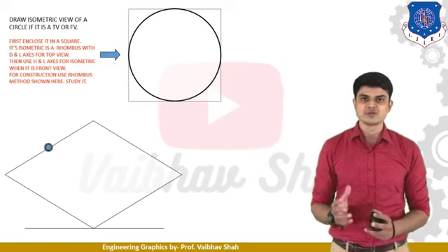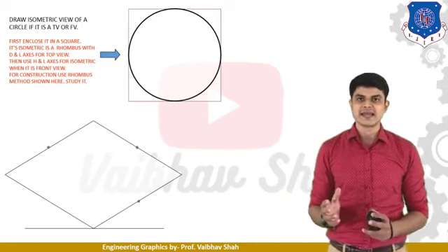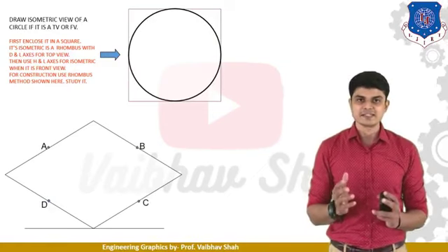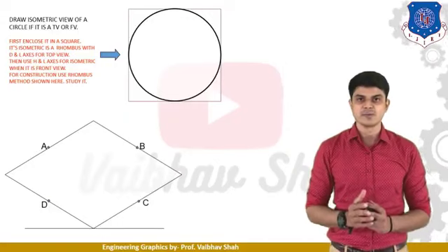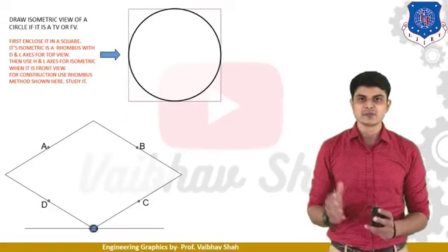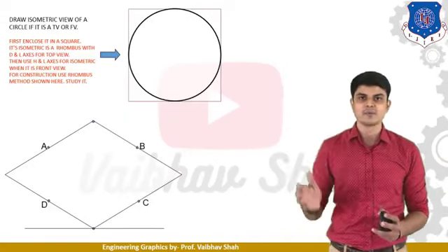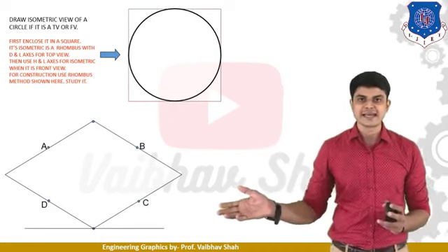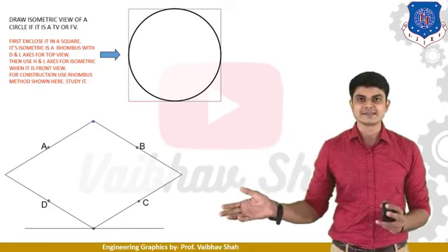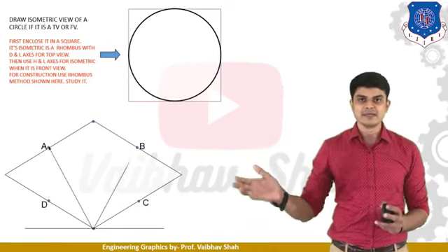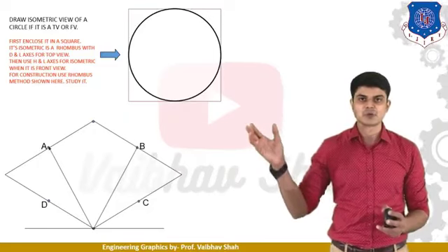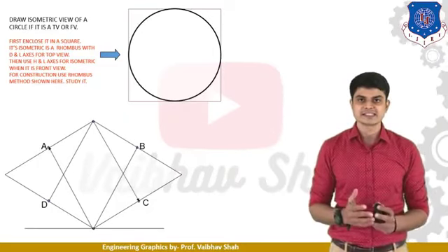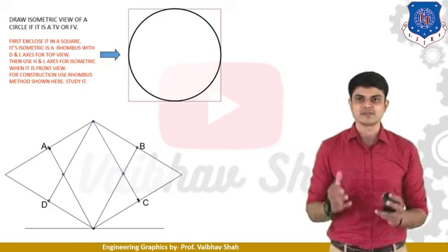After getting the rhombus, you need to find the midpoint of each and every side, and mark these points as A, B, C, D as you can see. Now let us find the shortest diagonal of the rhombus and highlight the points. The vertical points are the shortest diagonal of the rhombus, so I have highlighted the points. Now from the bottom point of the shortest diagonal, let us join the opposite sides, like A and B. Similarly from the upper point of the shortest diagonal, let us join the points B and C. So we will have two intersection points. Let us highlight these two intersection points of these lines.